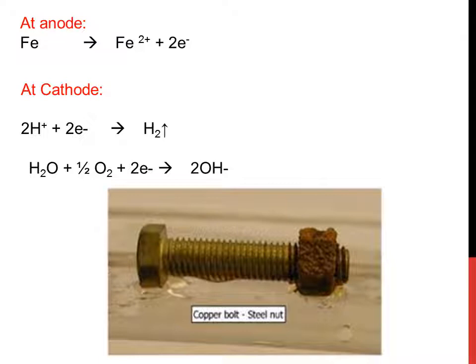less susceptible to corrosion. And also we can avoid the unfavorable area effect of small anode and large cathode. So we have to design the material in such a way that it will avoid the smaller anodic area and larger cathodic area. And whenever there are dissimilar metals, wherever possible we need to try to insulate the dissimilar metals.